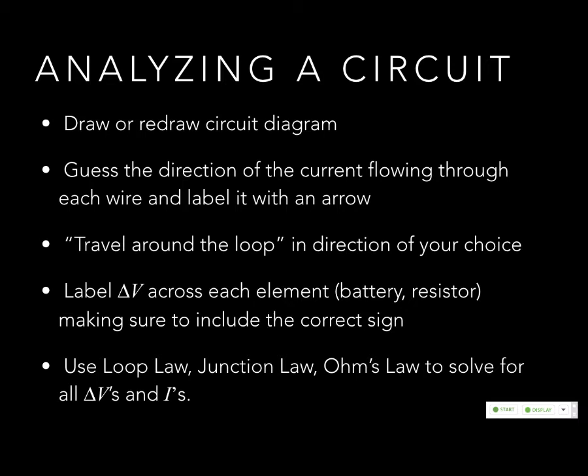Travel around the loop in the direction of your choice. Now remember, any loop you could pick clockwise or counterclockwise, it does not matter. It also doesn't matter whether you guess the current right or wrong, because if you guess wrong, what happens? You just get a negative sign at the end, okay? So as long as you pick the currents and you stick with them till the end, you'll get the right answer, okay? So you have to guess the currents, you have to pick a direction for your loop, because remember, you have to pick a direction for current and for travel, okay?